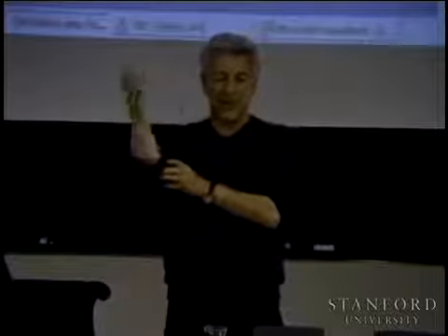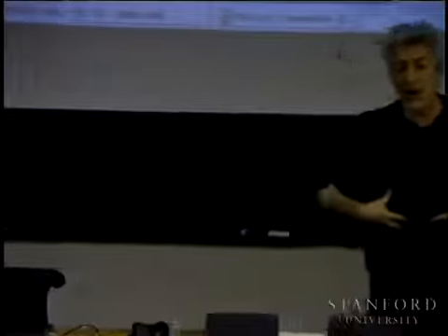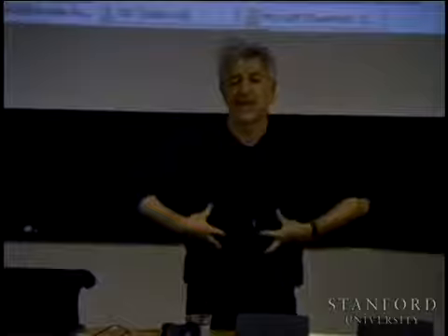Encoders, yeah. Encoders measure 1 degree of freedom, just the angle. And how many encoders do we need for 47 degrees of freedom? 47. Now, that will give you the relative position, but we will not know whether this configuration is here or here, right? So you need a GPS to maybe locate one object and then locate everything with respect to it.